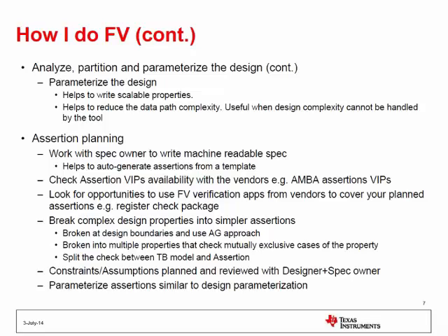For example, from Cadence you have those AMBA VIPs already available. I think there are some more they support. If they are already available, you don't have to do any work. All you need to do is interface your DUT with those assertion VIPs and you are good to go from day one. I mean, it is not day one, it takes a couple of days to figure out the right configuration, but at least you don't have to spend a couple of weeks to write your complete set of assertions.